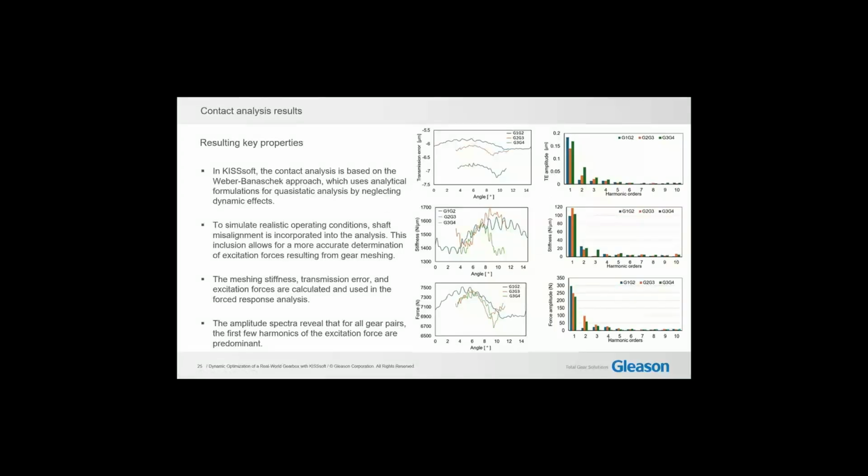After building the model, we do the contact analysis. In KISSsoft, the contact analysis is based on the well-known Weber-Banaschek approach and uses analytical formulations for quasi-static analysis. On the right side, you see that the transmission error, stiffness, and excitation forces in both time domain and frequency domain are shown. And according to the results, especially when focusing on the results in frequency domain, you realize that